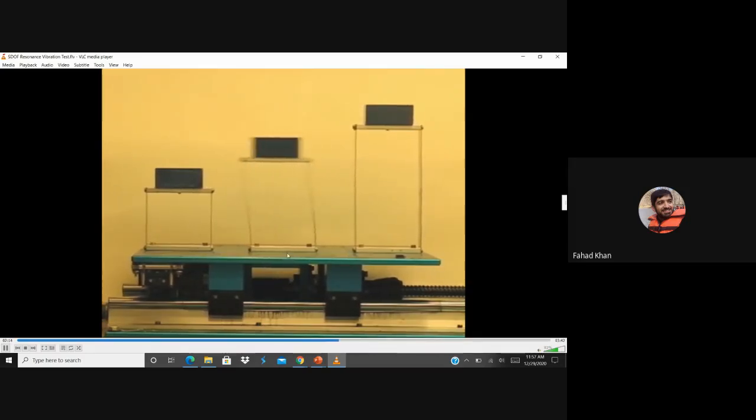And now we have increased the frequency even a bit further. Now the tall structure doesn't seem to be vibrating at all, while the rigid structure, the smaller structure, is vibrating, and so its frequency is going to be at 11 hertz. But look at the response of the flexible structure at a frequency of about 11 hertz. You will not see any displacements here or here. So let's check our formulas and graphs and see where we stand.